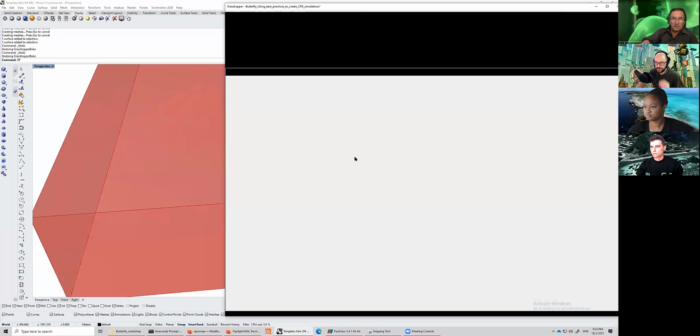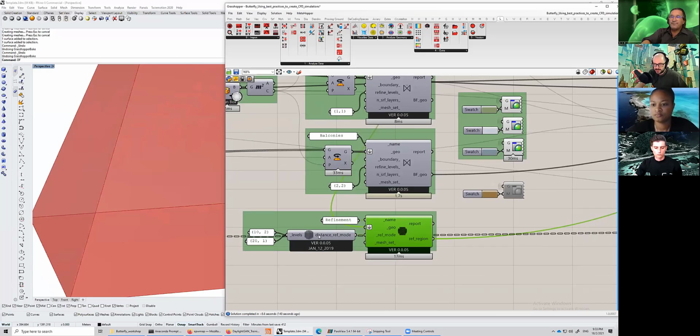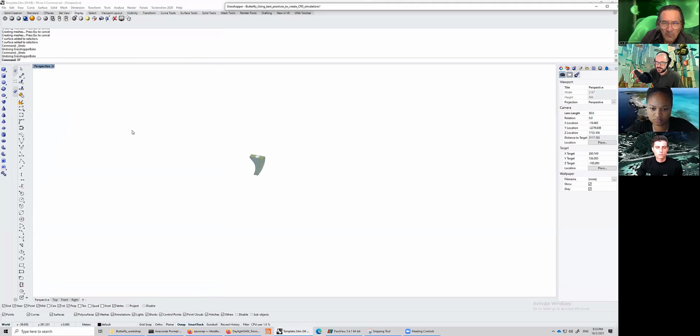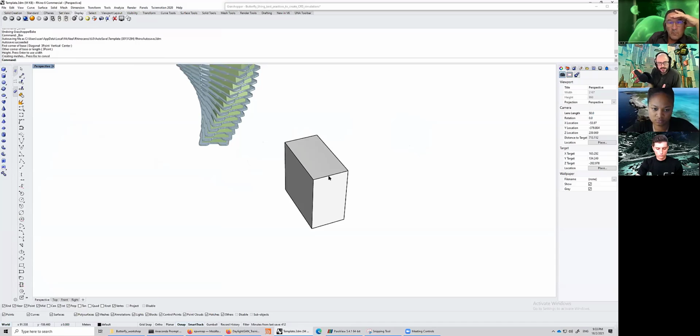And my best practice with Butterfly, because we have another component that I will show later, is to use this distance refinement mode. And I will explain now, with Rhino, what this means. What is the distance refinement? Let's say that we have a little box here, and actually it's very big, that we want to refine. And we want to refine the area around it, right? It's very important for us that around this area, we have more refined things.